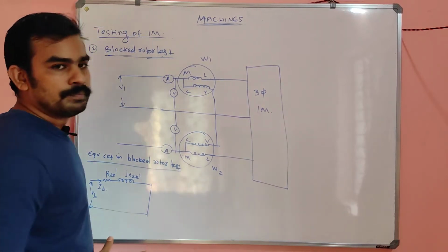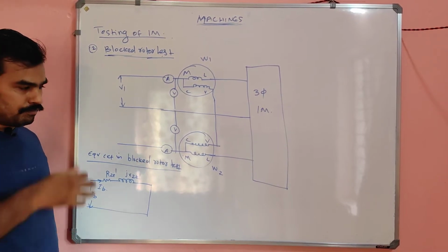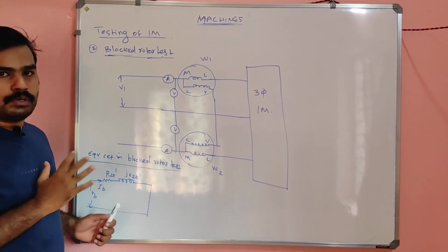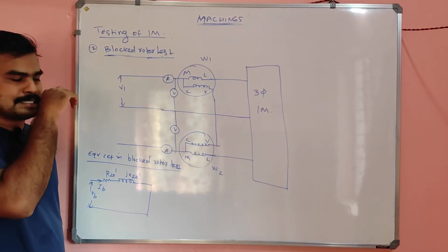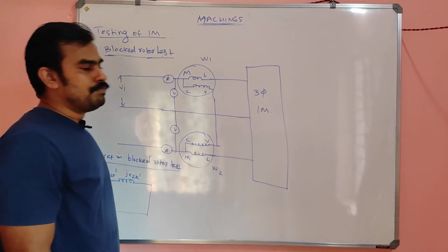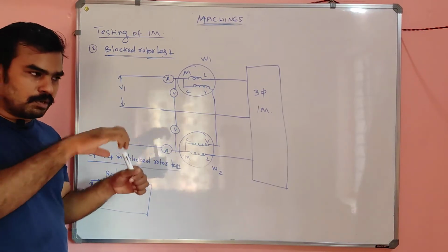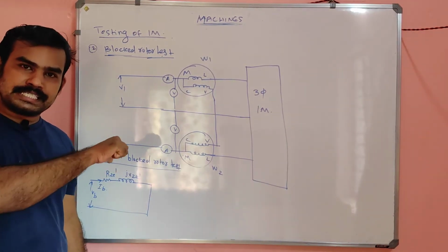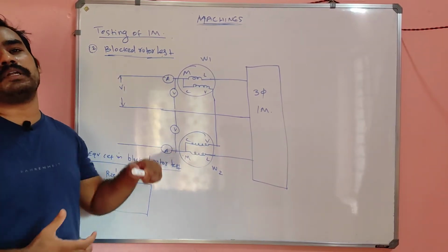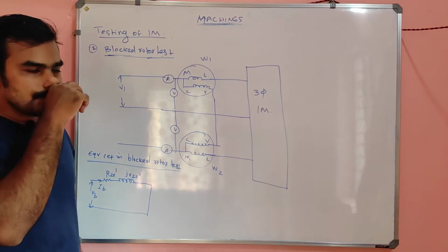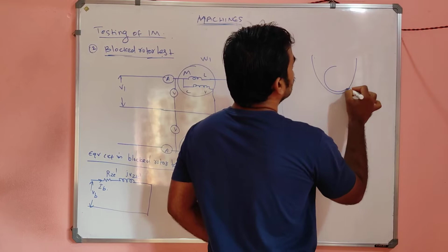Okay. So now in the blocked rotor test, we have to apply the rated voltage, and there will be some current, of course, which is nothing but the no load current. On the rotor side, the induction motor shaft is called the rotor. We have to block the rotor slowly, by using a pulley arrangement. I think you already did this in the laboratory.